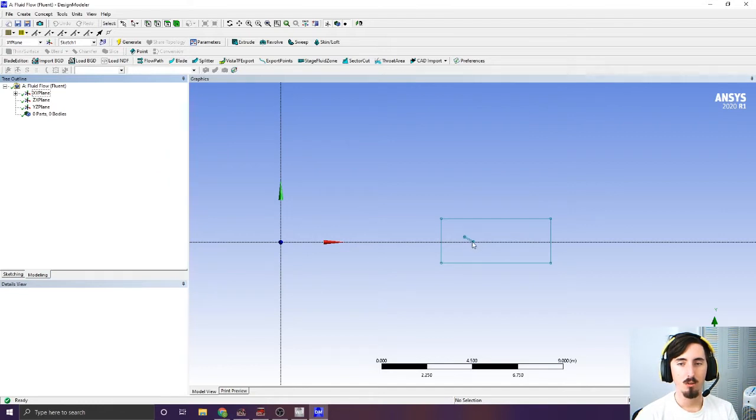Then you use the 3-point rectangle to follow the line that intersects with the x-axis, and then use the line itself to snap to, and then extend that out, and then you'll use the dimension tools to create your own dimensions, whether that's, right now we're using 5 centimeter thickness with a 50 centimeter length.